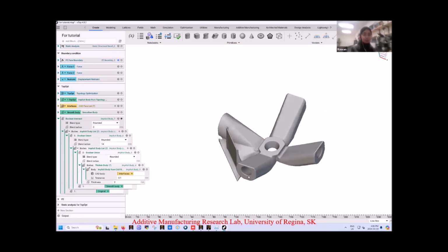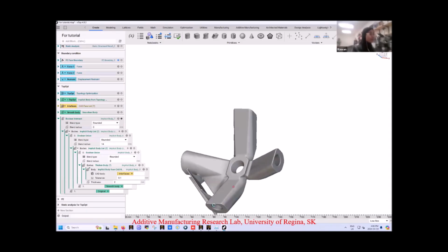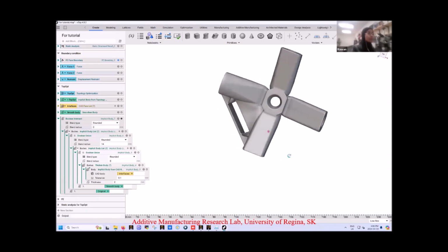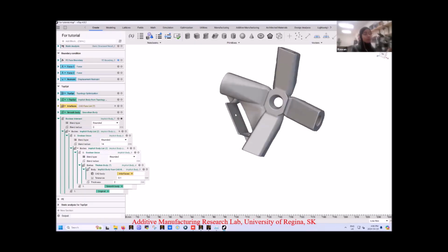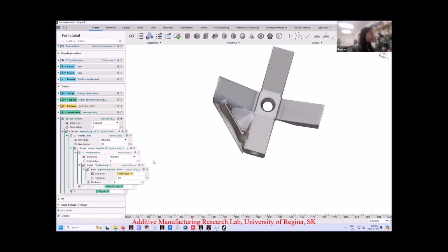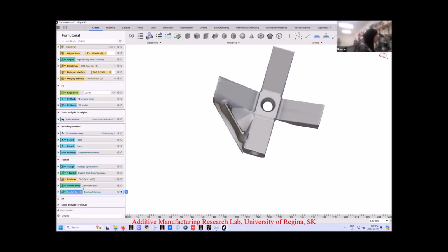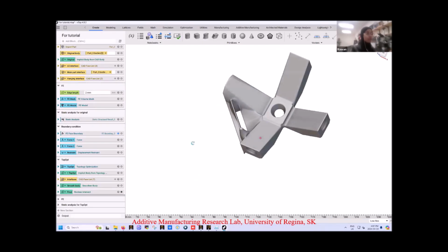That's the result. And if you're having trouble with your results, that means you maybe didn't define the faces that you want in a proper way, but it's an acceptable version. So you have your areas that you want to preserve, and you have the qualities of them. So that's a Boolean intersect. And these are the parts that we want. We can increase this one again, just in case you have a better result. And that should be the final result of our topology optimization. We can make it a variable and call it the final. That's the final version of topology optimization in this case.